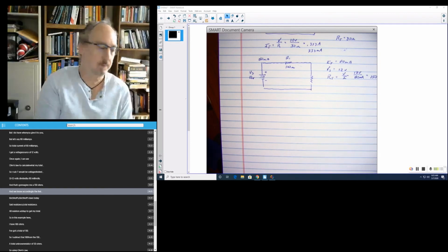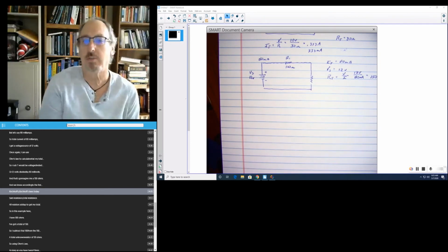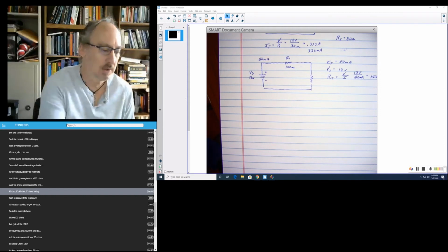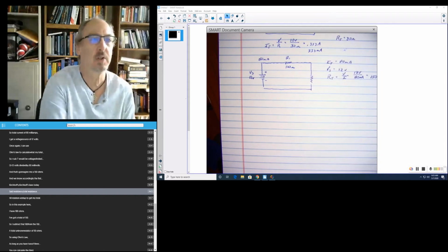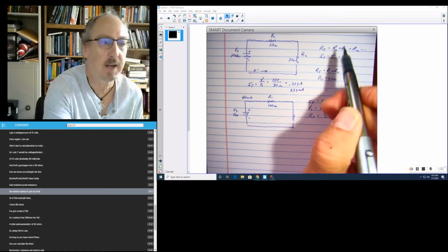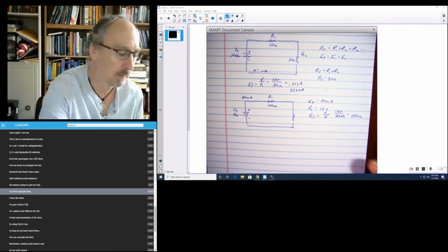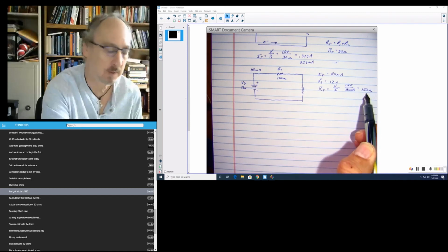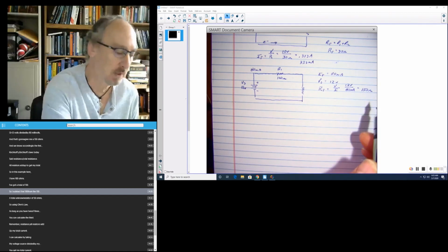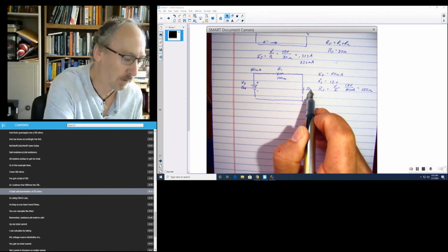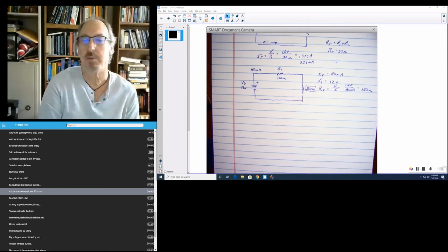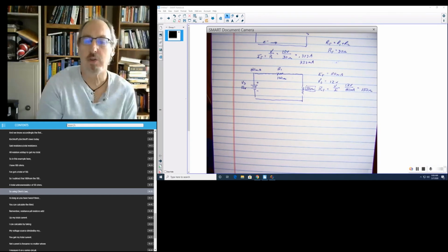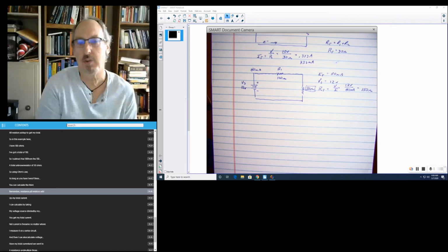Now we know, according to the first example, Kirchhoff's laws state that total resistance, all resistors add up to get my total. So in this example here, I have 100 ohms. I've got a total of 150. So I subtract that 100 from the 150, and I get an unknown resistor of 50 ohms. So using Ohm's law, as long as you have 2 of 3 variables, you can calculate the third. Just remember, total resistance, all resistors add up.